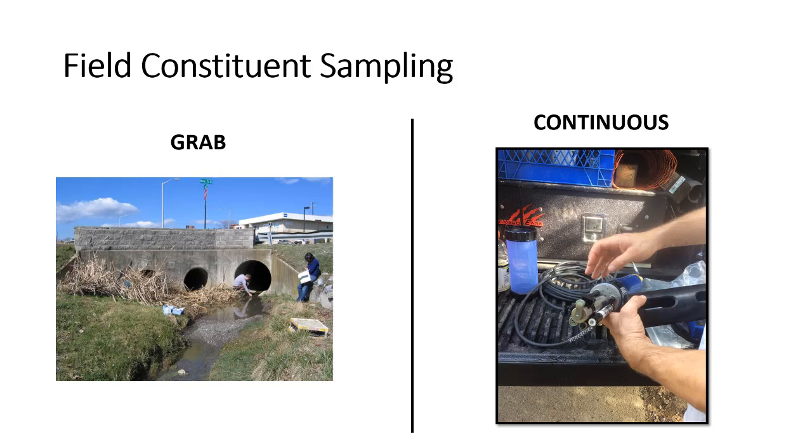This little thing in the middle is actually a wiper. That wiper circles around and cleans off some of the sensor heads, because they get fouled with all kinds of stuff in the stream, and that can really affect the measurement. This is a really nice tool. I think this particular one is giving measurements at a 15-minute time interval. I'm sure you could make it do it faster than that. But it's only able to collect certain parameters. We're going to talk about which ones it can collect and which ones it can't.